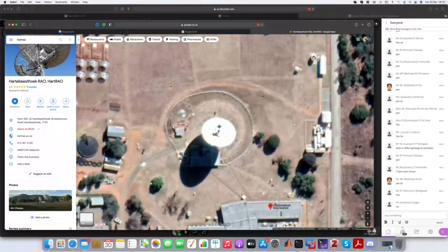So by doing that a couple of 100 times per day, we can see how it's moving, and by that we can determine the high tide, low tide effect. And we also use that to determine the heat effect, so for structures shrinking, structures expanding due to heat. So we need to use that information to calibrate our telescopes.